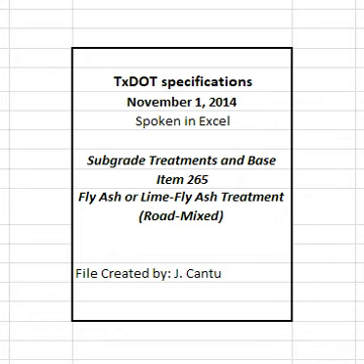3.3 Distribution equipment. Provide equipment to spread lime and fly ash evenly across the area to be treated. Provide equipment with a rotary vane feeder to spread lime, when shown on the plans. 3.4 Pulverization equipment. Provide pulverization equipment that cuts and pulverizes material uniformly to the proper depth with cutters that will plane to a uniform surface over the entire width of the cut, provides a visible indication of the depth of cut at all times, and uniformly mixes the materials.